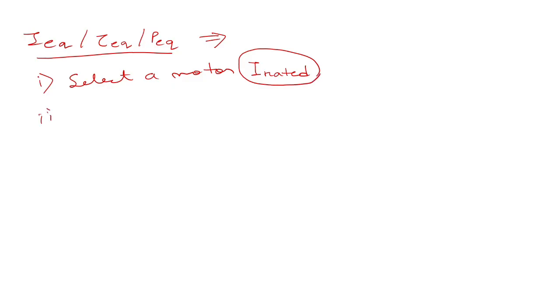Now we know for a DC motor, remember these steps are very important. For a DC motor, the motor can be allowed to carry a larger current than the rated current for a short duration, as the temperature rise is not instantaneous. Therefore the motor can carry a higher load than the I rated. That higher load is, suppose, I max, that we will get from the load diagram.